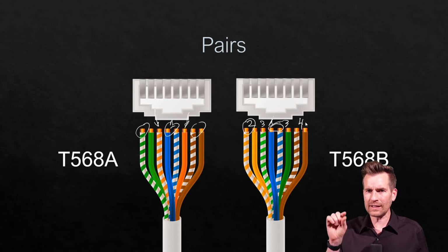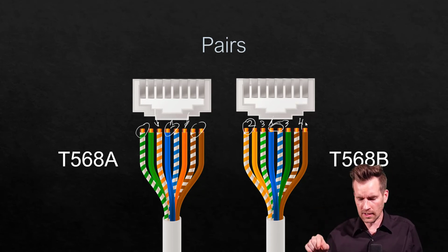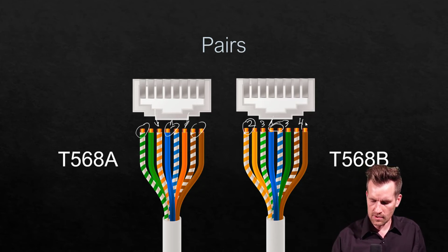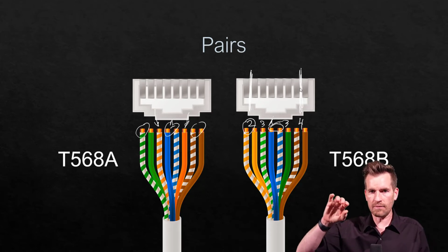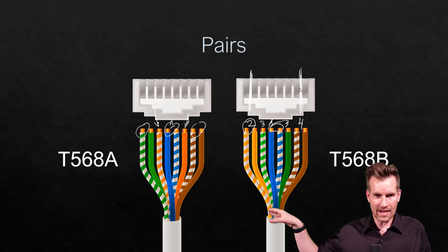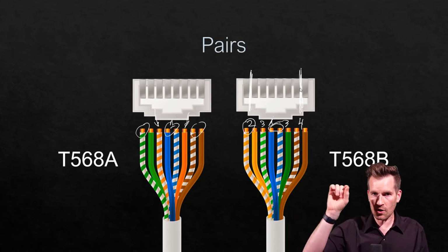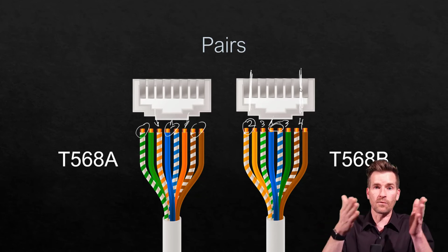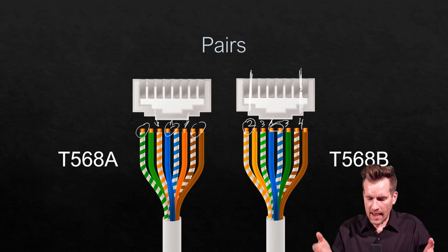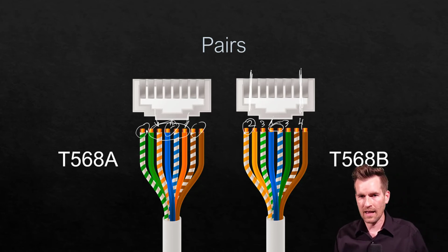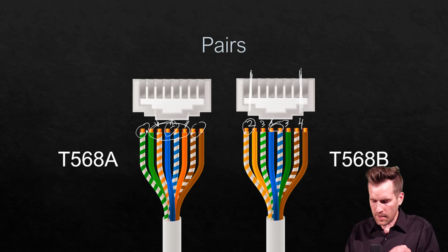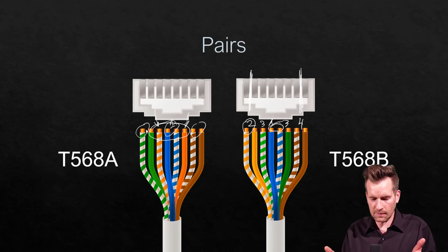And in fact, if you look at an RJ11, which is used for phones, the RJ11 looks very similar to the RJ45, except it's just a little bit smaller, and that's because it only uses 6 conductors. And you can actually still use all of your Ethernet lines from your patch cables and plug RJ11s into them. So you can use this either for data or for phone. And so that is one of the reasons for the odd space right here in the middle of these. But other than that, you can pick out how there are some similarities with these.